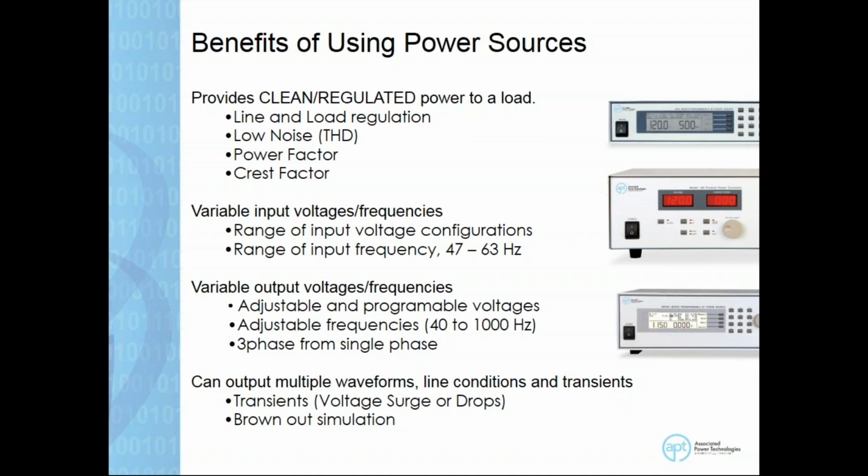Some of the requirements for airplane applications or any kind of avionics applications may call for a frequency of 400 hertz or 800 hertz, because of the power requirements for those applications. So these are typical benefits you get taking in a 60 hertz input and providing 400 hertz, 800 hertz, up to 1,000 hertz of output from the same supply.